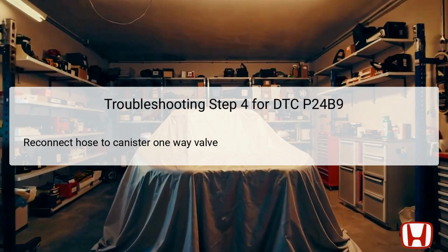In this step of the troubleshooting procedure, the technician reconnects the hose to the canister one-way valve. This is a vital part of the process, as the function of the one-way valve is to ensure that fuel vapors are directed appropriately within the EVAP system while preventing backflow.